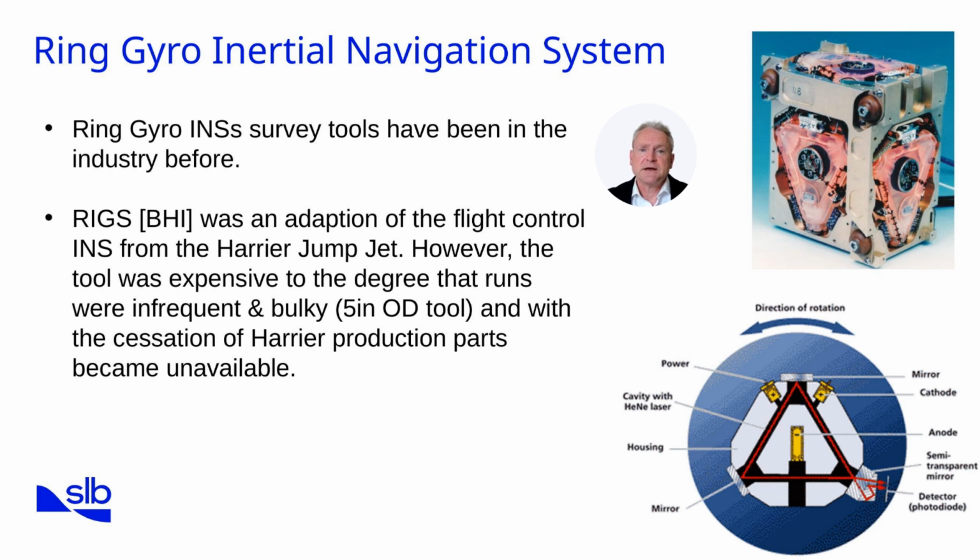Today, inertial navigation systems are re-emerging in smaller, cost-effective packages that utilize MEMS and optical technologies. They may soon dominate the market as cost comes down. The lesson from the ring gyro is that advanced inertial navigation can deliver aviation-grade accuracy to drilling, enabling wells with tighter tolerances and safer anti-collision assurance.